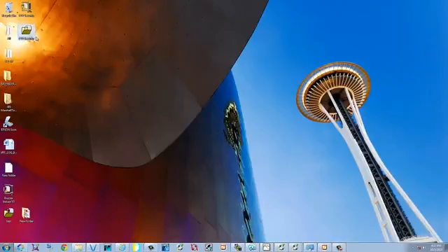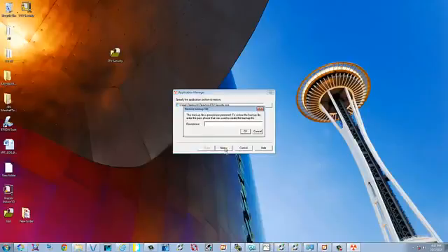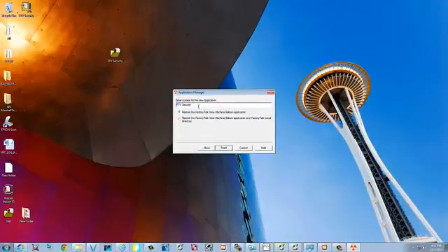Now we're going to show you how to use this backup file to bring an application back in. So just go ahead and double click it. We're going to restore this. Select Next. We didn't use a passphrase. Since we already have FactoryTalk View security already in our project, we're going to make another one. I'm going to select it as 2. Create, and make sure you select Restore FactoryTalk View Machine Edition application, and then select Finish.